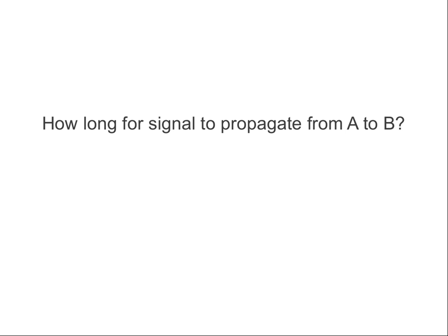So it's less than the speed of light, but for simplicity, we'll assume the speed of light is the speed at which a signal travels. 4,500 meters divided by 300 million meters per second is our 15 microseconds.